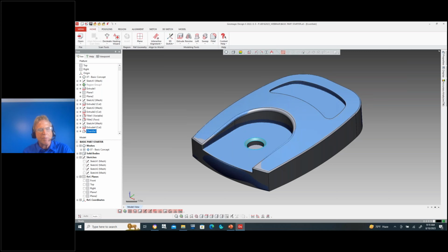One thing I want to point out here is when we build a CAD model, we're creating a model with perfect dimensions, right? So the CAD model is absolutely perfect, but when you scan parts, you're limited in a few ways. Number one, the part that you're scanning has been manufactured, so it's not perfect geometry. Number two, the parts are generally worn, so they're even less perfect. And then number three, your scanner most probably has a little bit of error built into it.